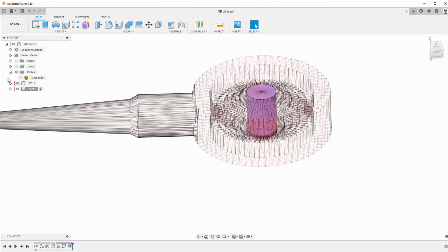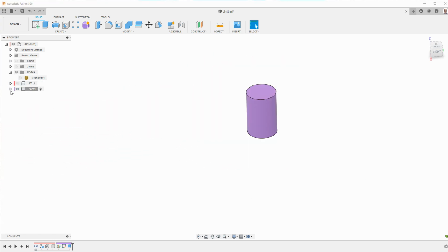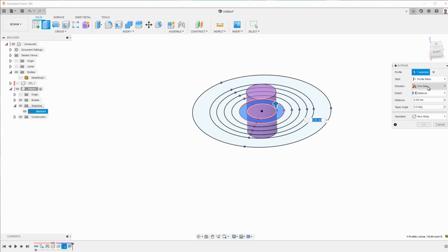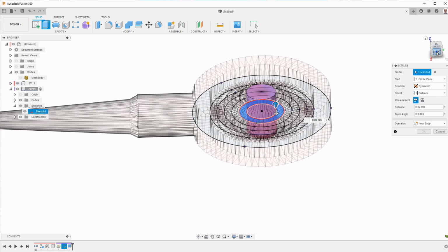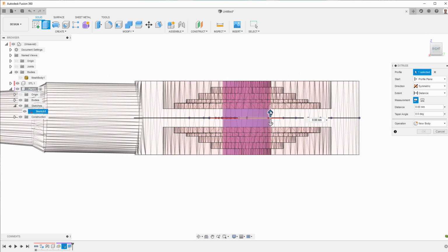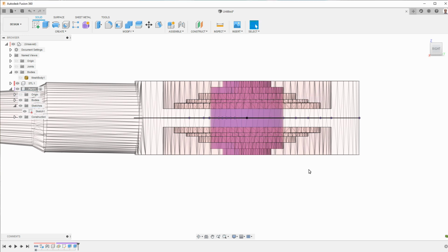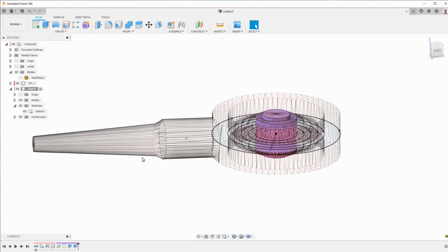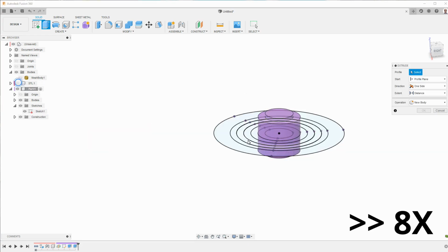And then I want to do the same thing with the next circle. So I have to turn the sketch back on. Extrude, symmetric, STL back on. And let's see what this looks like. So this looks like it's probably 2.5 millimeters. So already what I'm doing is I'm trying to make these things regular numbers to try to guess the intent of the person who gave me the file.